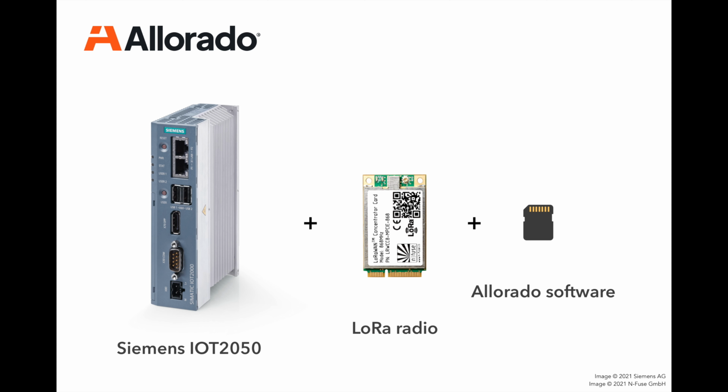In this video, we assume that you have basic knowledge about the LoRa protocol, as this is not an introduction to LoRa, but rather an explanation on how to configure a LoRa device on the IOT2050 and use the decoded payload information in NodeRED. Via the web interface, you will be able to set up a LoRa device within minutes and see the data coming in. There is a whole library of sensors with already built-in support, so the decoding happens automatically and is seen in NodeRED and on the web interface.